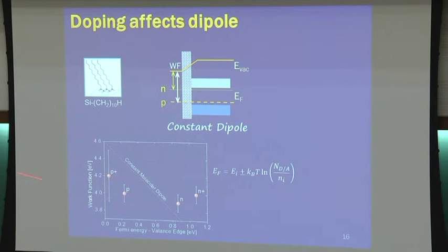This is the measurement of the work function by UPS, and you see the dotted line is what we expected to see, and that's what we do not see. So the work function is more or less constant. Maybe we have some U shape, but the work function is basically indifferent to the doping of the silicon. So we wanted to understand, and we know very well that our surface has very few surface states. I showed you before that we could change the barrier height efficiently. So we don't believe that it's because of some Fermi level pinning due to surface states.